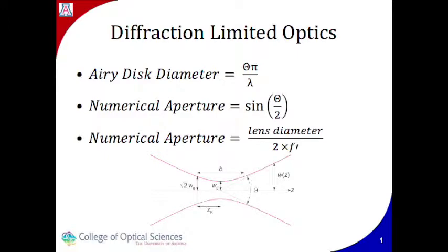In certain systems, such as a DVD player, a high numerical aperture is desirable to image the smallest spot size in a very limited amount of space. In order to achieve this, one can use a very large diameter lens, which is not possible with mechanical constraints in a DVD player, so a very small focal length must be used. Measuring a very short focal length of the lens is difficult, but luckily we have the nodal slide to assist us.